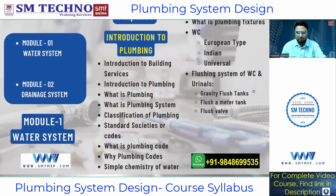So make sure whenever you are dealing with any kind of project, you need to get some inputs, okay? That means it depends on the kind of project. For example, if you're dealing with a commercial project, you will mostly have a flushing system with a flushometer valve or flush valve. The reason behind that is the occupancy for those WCs or urinals in a public toilet is more, because it is in the public category. That means the usage of that fixture would be more when compared with the domestic.